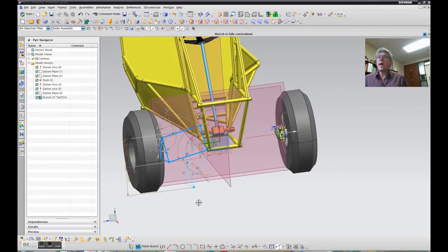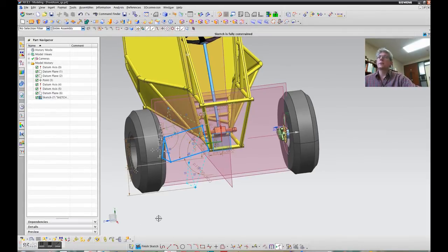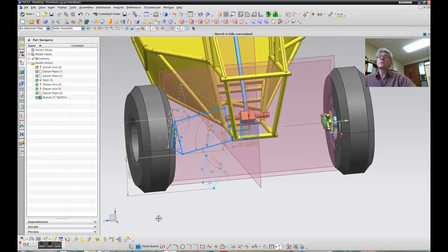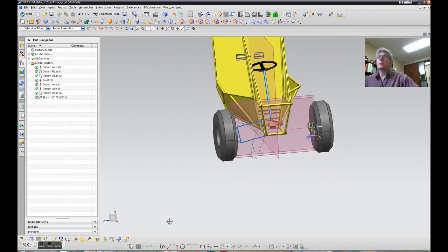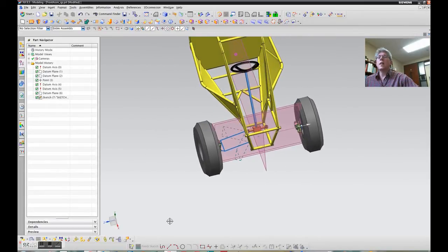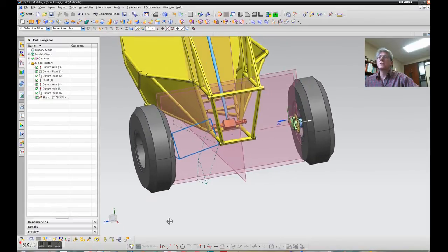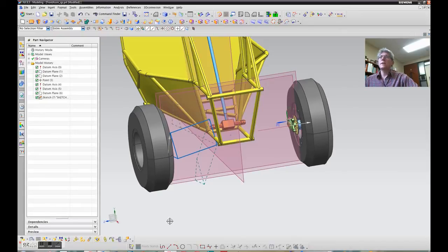So I don't even have any parts as of yet, but I figured I would at least show what I have. I think we can all agree that probably the most urgent requirement, let's put it that way, maybe it's not the most important, but the most urgent requirement, is to design the mechanism, the linkage for the suspension such that we have the travel. It articulates the 8 inches up and down, keeps the wheels parallel, doesn't run into anything.